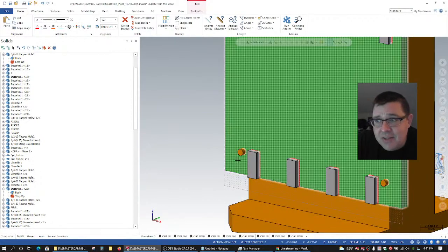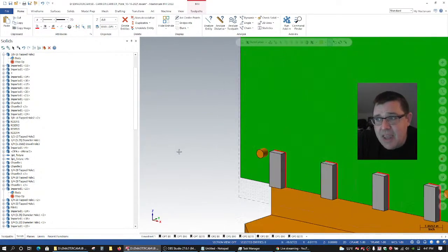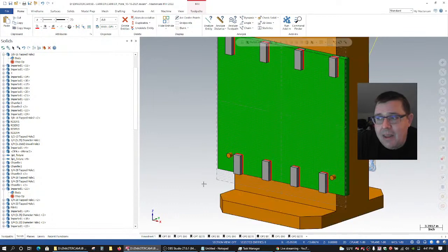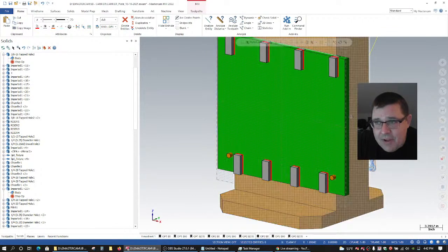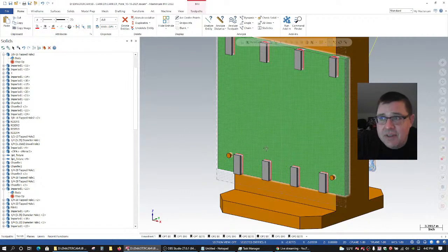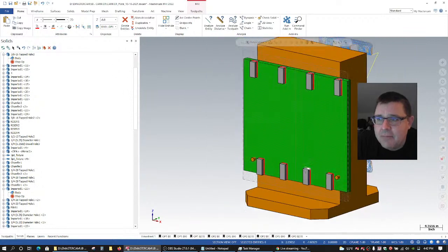So I'm going to take these clamps just like this, and in my OptiRough avoidance geometry, I'll select the top face of this pin. I'll select the top face of each of these solids, and maybe, the top face here or the edge face of this fixture plate, but that's kind of it.